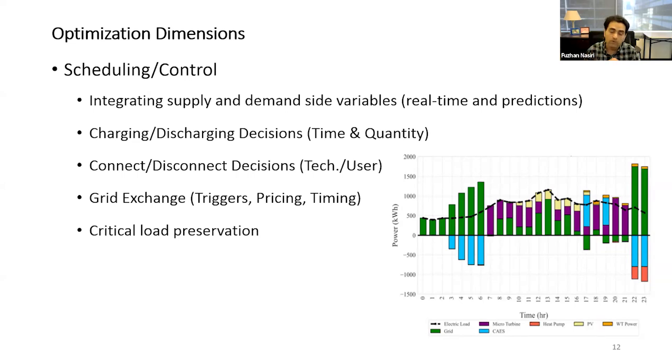I mentioned before, when we talk about energy storage, there is always a lag in charging and discharging. So scheduling decisions to benefit from energy storage need to be made ahead of time. You cannot expect energy charge and discharge to be used on a real-time basis. It takes some time, and that creates a lag. Sometimes this lag is short, in the case of batteries. Sometimes this lag is long, in the case of mechanical systems.